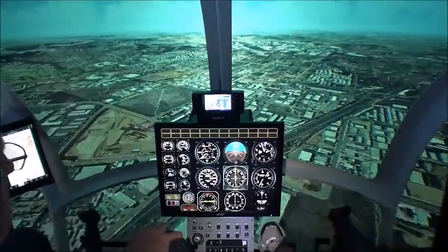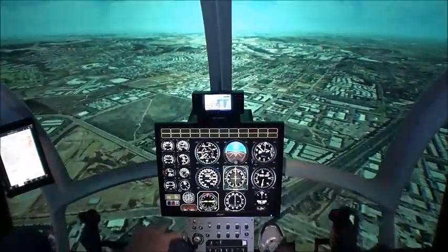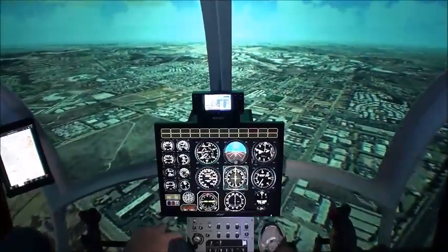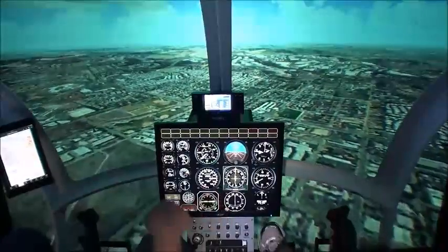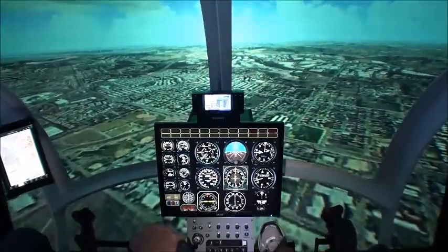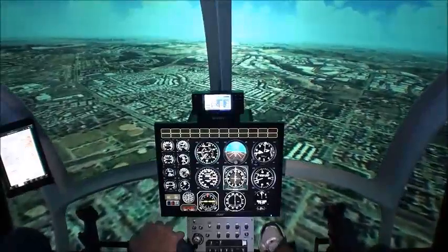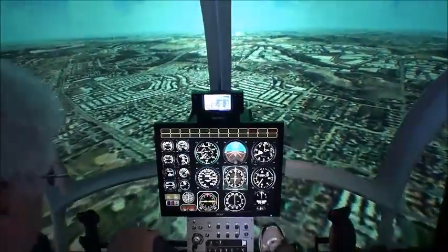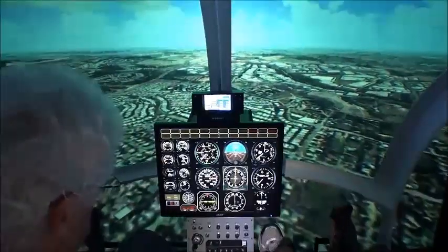Okay, clear to continue. And now at Gujik we need to be at 2,040 feet, but as long as we're on this glide path, we're okay, and we'll go down to 737 feet, which will be 411 feet above the runway. And just as a backup, we can't fly according to this, but I wanted to show this working.